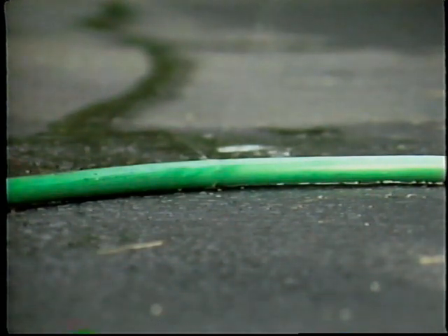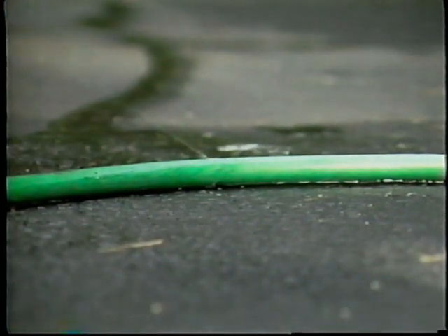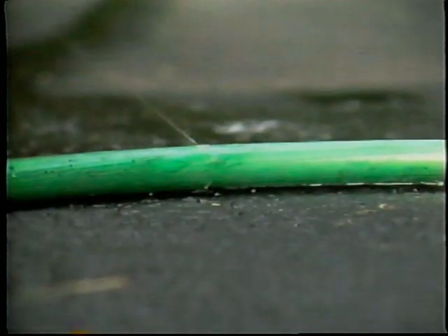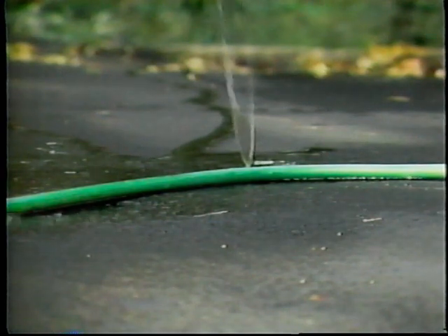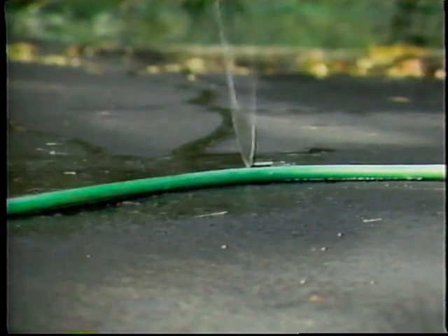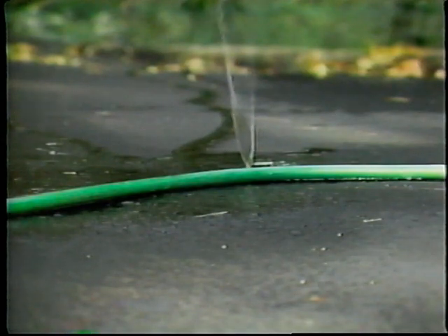The hole in the hose is an orifice. If the hole in the hose is small, as we have here, the flow is limited. It appears as a drip or spray. But if the hole is large, as we've purposely made it here, the leak will be a stream of liquid. So you can see, by varying the diameter or cross-sectional area of an orifice, we can regulate fluid flow.